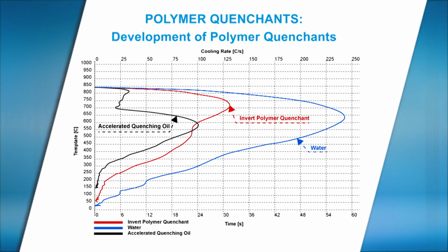Heat treatment operations can be carried out with these water-based quenchants, which would either be impossible or extremely difficult with oil. This particularly relates to spray quenching in induction and flame hardening processes, where a high degree of fire risk exists when using oil.